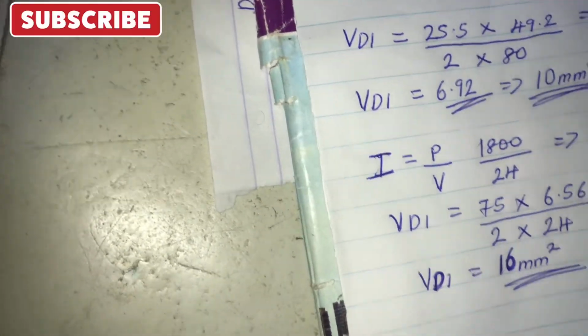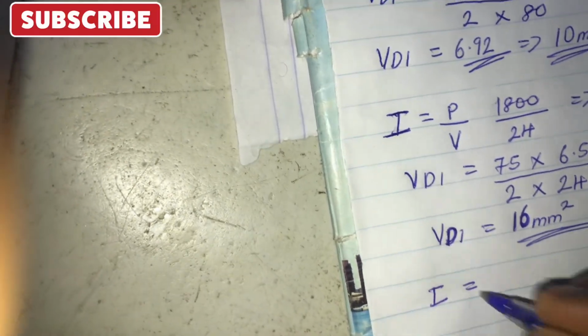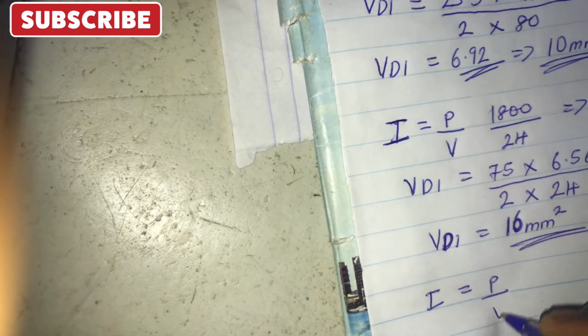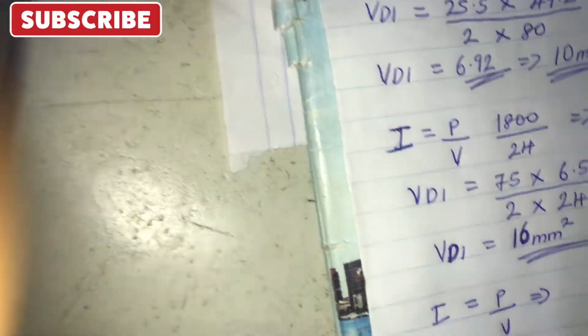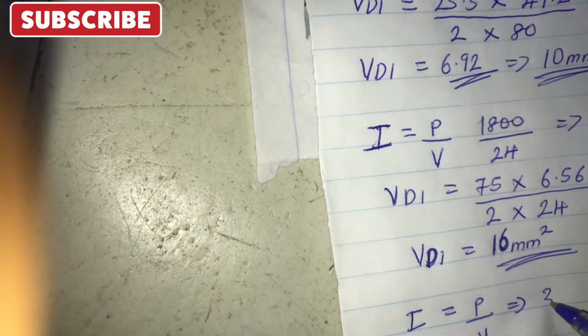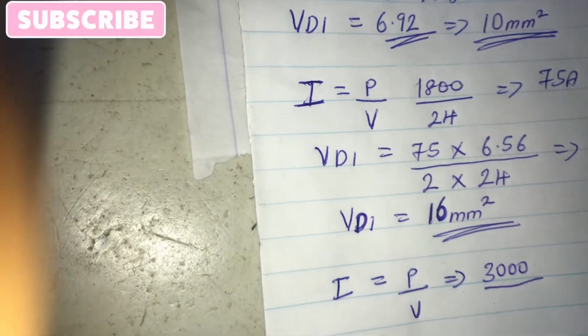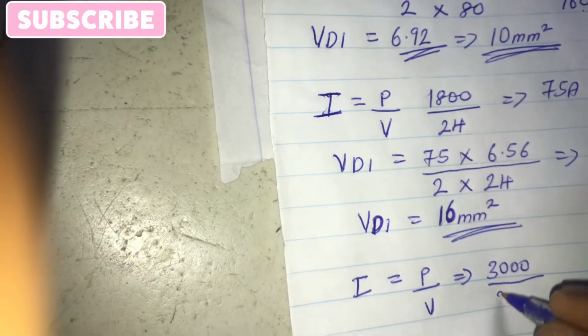So just as we did before, we are going to find the current first, which is power over V. The power in this case will be the power of the inverter, which is 3000 watts, over the voltage. You can use 220, you can use 230. In my case, I'm using 230 volts.